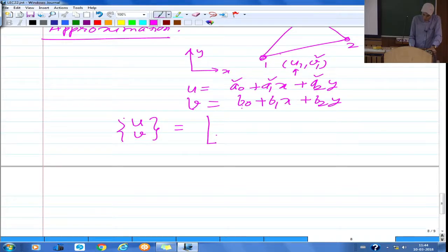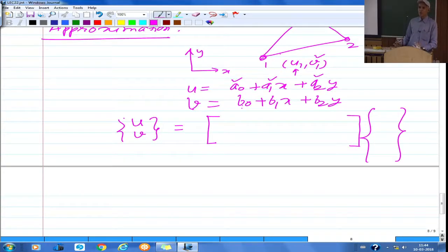But then what we want to do is write this in such a way that we put all the elemental degrees of freedom into one vector. Typically the procedure is that first we write all the degrees of freedom, although one can change this, in this elemental vector corresponding to the first node, then the second node and the third node.